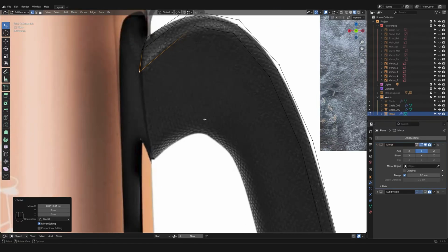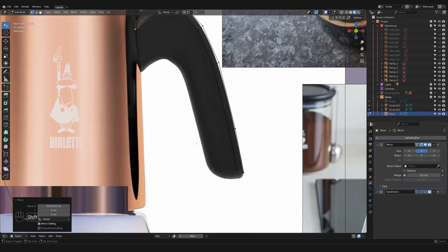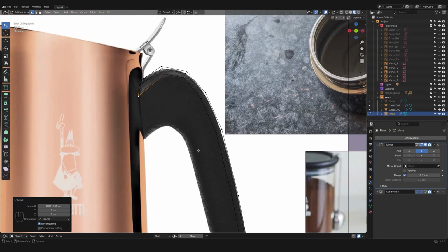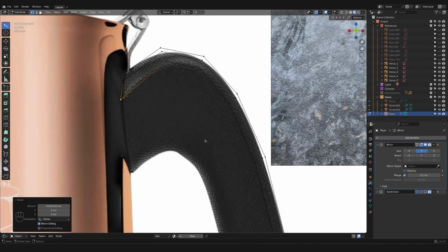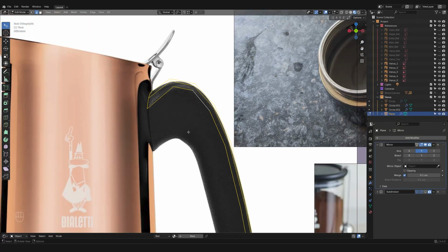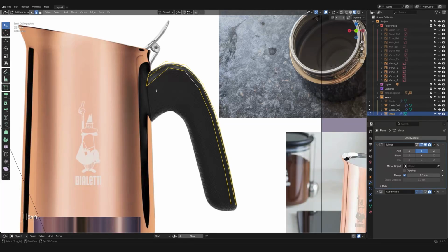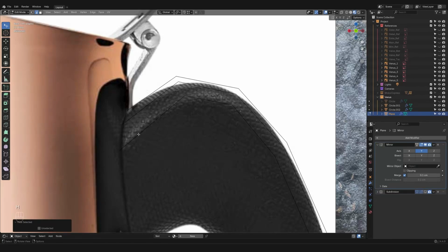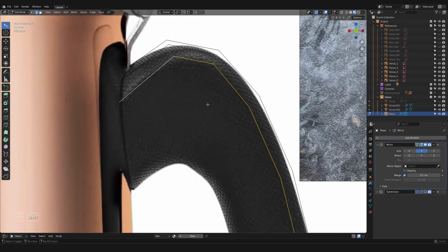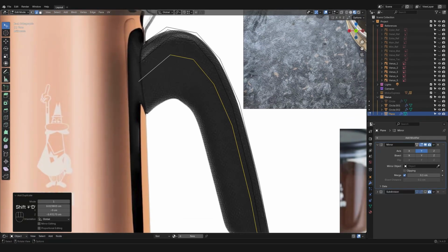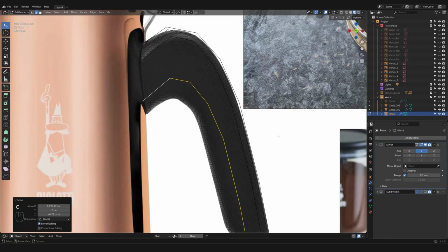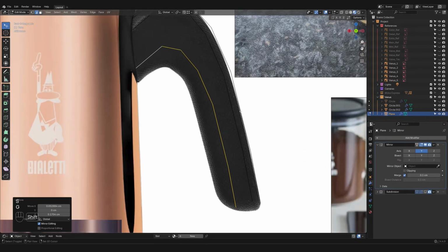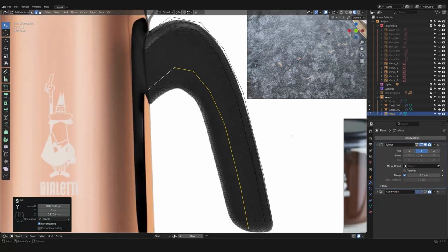And let's see. Here we have another change of plane, although the sort of radius of the bevel is much bigger. Right now, if I try and select everything, and I mean this part, it's gonna actually select everything, like everything, because I've connected them. So I'm gonna hide this one for the moment, select the part that I'm interested in, Shift+D, duplicate. Never do the job twice if you can recycle. It's good for the planet and also good for you.